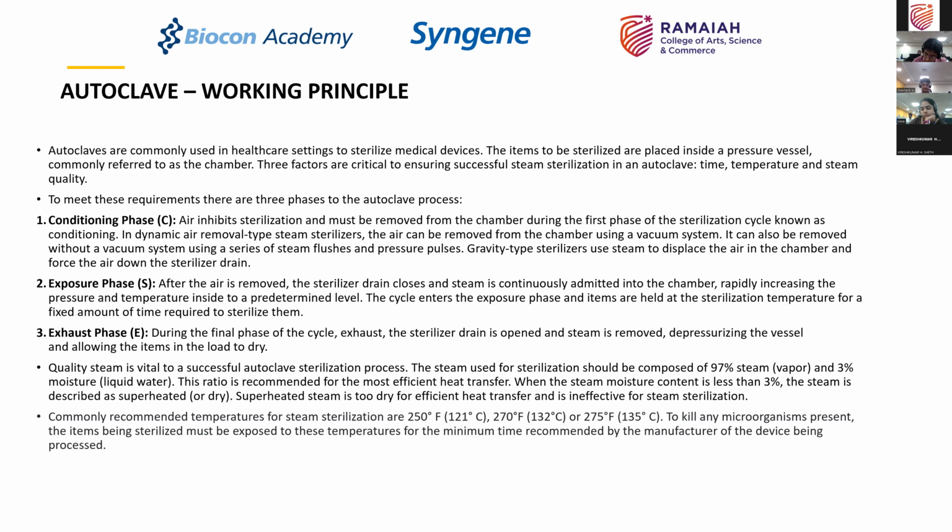Then the exposure phase, of course, where you admit the steam continuously into the chamber, increasing the pressure and the temperature inside to a predetermined level. The cycle enters the exposure phase, where the items are held at a sterilization temperature for the fixed amount of time required to sterilize them. So this is the time when you initially do the air removal, followed by heating to a temperature of 121 or 123 plus or minus 2 degrees centigrade at a pressure of 1.2 when we refer to saturated steam, or an equivalent of that saturated steam's pressure and temperature condition, and therefore you expose the items to that for a prefixed time.